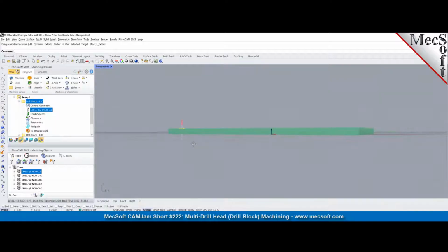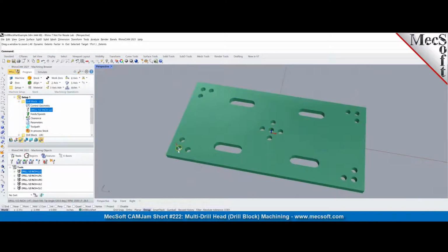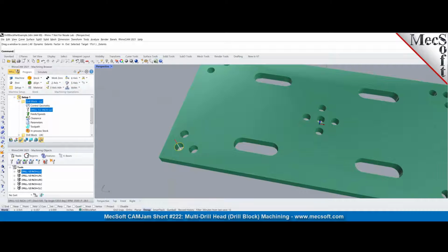I really don't care about the depth at this point. This is just for illustration purposes. And now, even though I'm just programming the anchor bit, since I'm using the drill tool, which has the binary code encoded, when I create this tool path and output it using the correct tool path post processor, it'll be decoded correctly. So let me show you that.